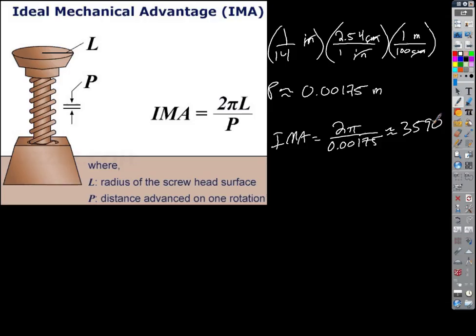That's a really big handle too. Well, if you wanted to jack up a house or something, you'd probably have that big a handle. I feel like the handle might break before it actually gets pulled. Even if it were a terrible mechanism, what if that thing were only 25% efficient? That's still a mechanical advantage of almost 1,000, right? Yeah. So every pound of force you apply, you'd get 1,000 pounds back.